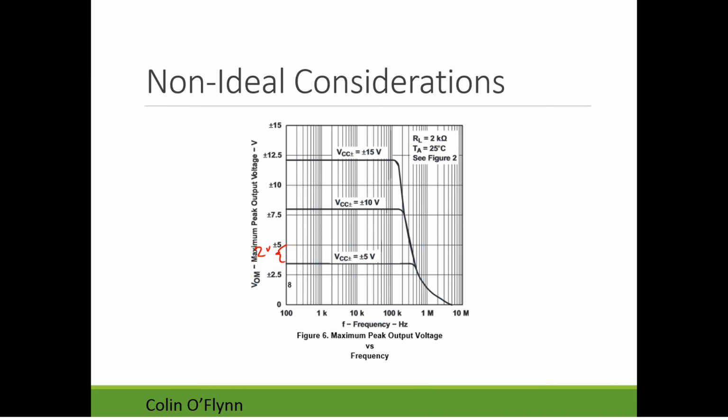What this means is that if you try to power an op amp from 0 volts and just 5 volts, you'll need to use higher voltages. The output can only go from 2 volts above the negative supply, which in your case is 0, to 2 volts below the positive supply. So the output of your op amp can only really go between about 2 to 3 volts. It simply has these limits in what voltages it can represent. So how do you solve that?